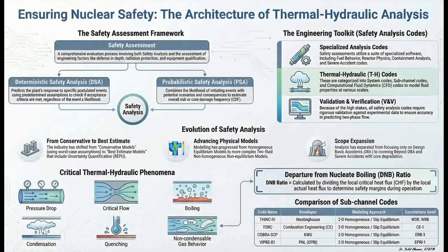To prevent that, the simulation must predict the precise microsecond that vapor film will form. The slides outline the specific empirical correlations the codes use to map this physical reality. And the mathematical rulebook actually changes depending on where the fluid is on the boiling curve. Yes. For standard, highly efficient nucleate boiling, RELAP5-3D relies heavily on the Chen correlation.